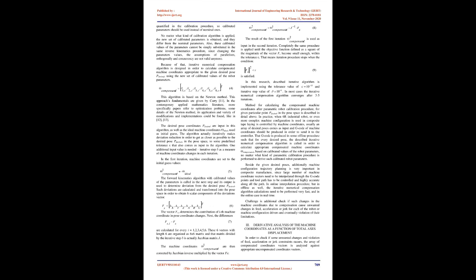More details on how to include non-geometric parameters in the mathematical model are given by Cammarata et al. [9]. In this research, different loads are used in order to examine the impact of stiffness parameters. Experimental data refer to the ABB IRB 1600 robot, and the maximal positional error is 0.960 mm if stiffness parameters are used, compared to 2.571 mm if just geometric parameters are used.